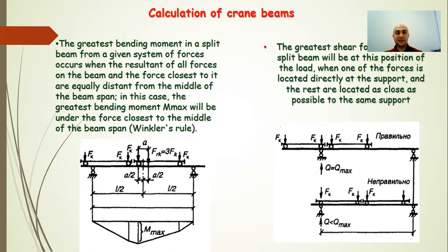The greatest shear force Q max in a split beam will be at the position of the load when one of the forces is located directly at the support, and the rest are located as close as possible to the same support.